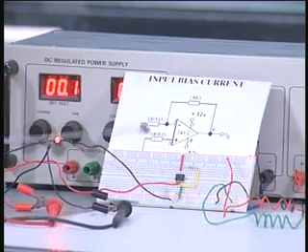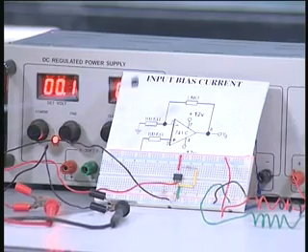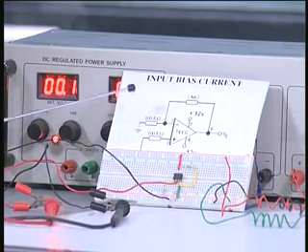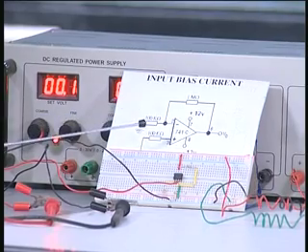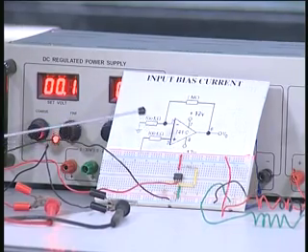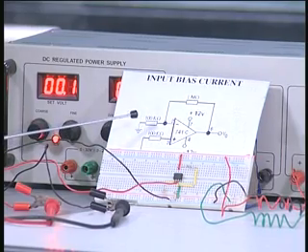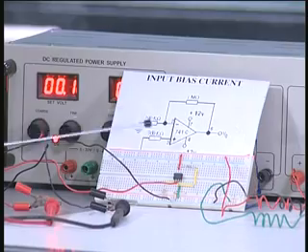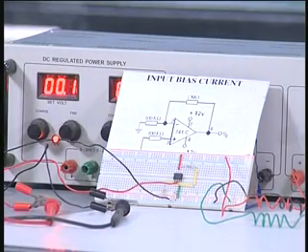terminal. So it is very easy to measure the input bias currents, and if you want to know the input bias current, you find the average of 47 and 37 nanoamperes. That gives you the average input bias current, and the input offset current is the difference. So we can calculate the input bias currents and the bias current offset.